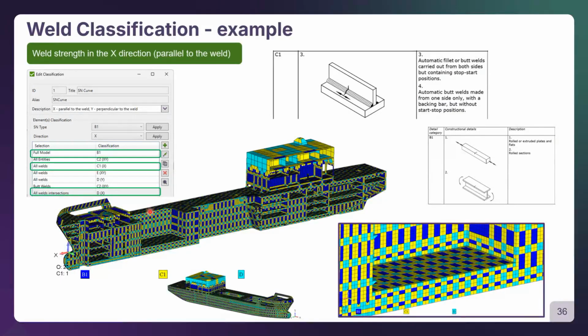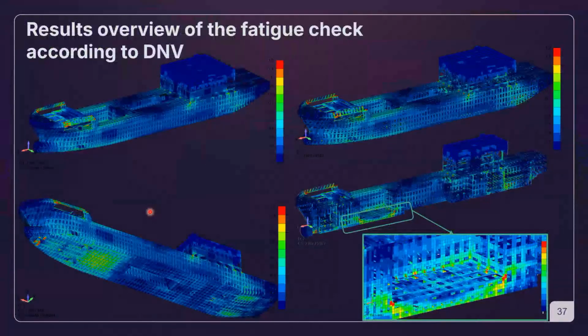Here also another thing which is obviously important, taking into account non-standard loads, as we discussed, which may result in much higher delta stresses, which again may result in very high probability of fatigue, is that with SDC you are able to check the fatigue of your structure in a much quicker way than manually. It can be done very quickly by assigning the classes for different welds, and later on obtaining the results,